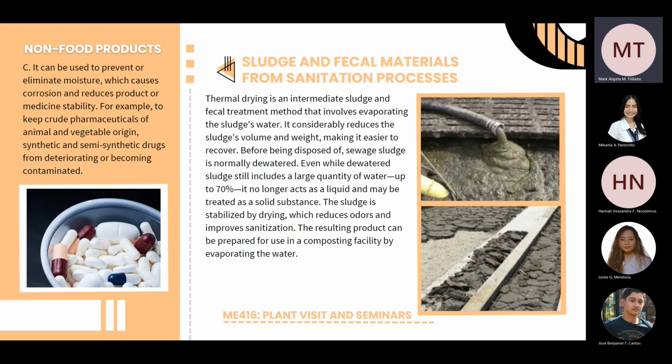Even while the watered sludge still includes a large quantity of water, up to 70%, it no longer acts as a liquid and may be treated as a solid substance. The sludge is stabilized by drying, which reduces odors and improves sanitization. The resulting product can be prepared for use in a composting facility by evaporating the water.